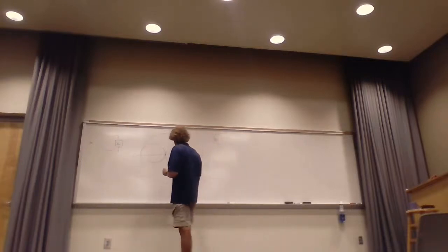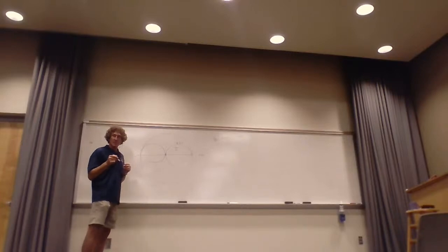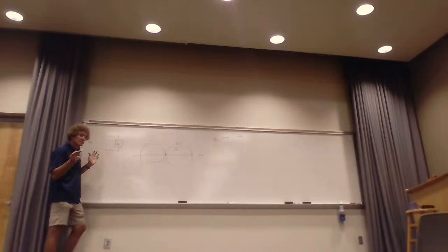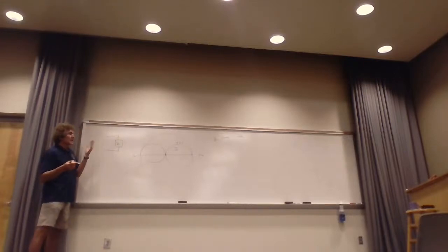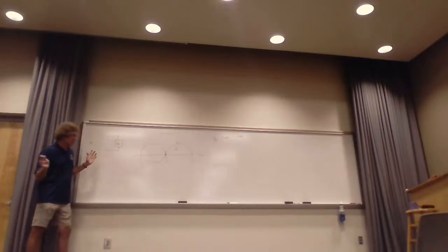The only thing that means, by the way, is that the real part of the normalized impedance is less than 1, because R=2 is here, R=3 is here. That's the only thing it means. You could just as well say the real part of normalized ZL is greater than 1, and it's the same thing.